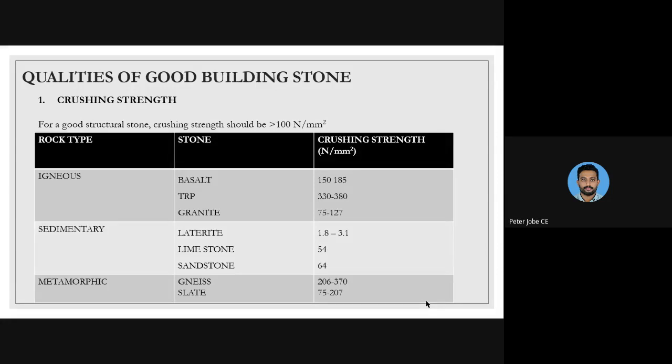You need to understand that structural stone means those stones which we use to transfer loads safely: foundation. As I have said earlier, the stones used in foundations are structural stones, and also the stones used in load-bearing walls, where no pillars or columns are available. The slab or the roof will be directly supported over walls, and in those places also we use structural stone. Bricks are also used, but I was talking about at what places the stones are used.